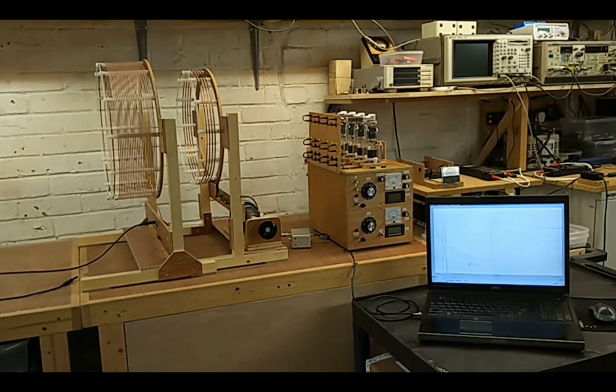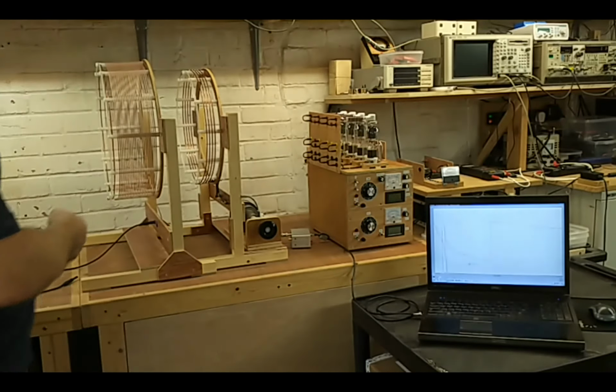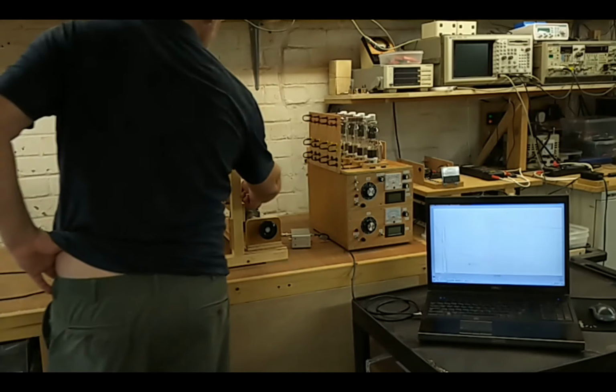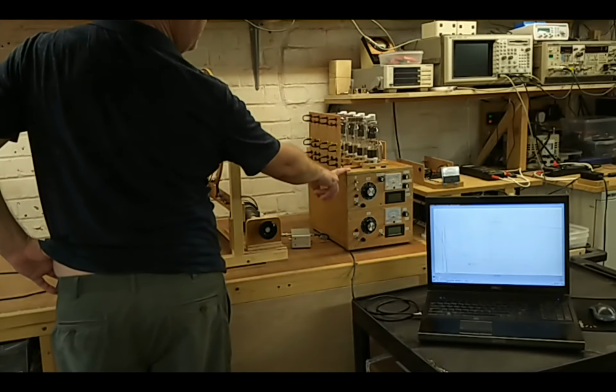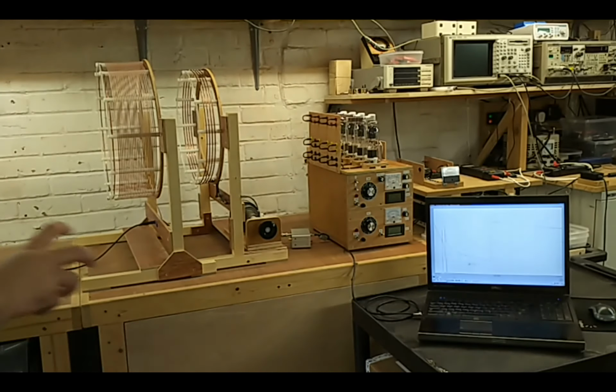at the impedance measurement. So this is all going to be about Z11, the small signal AC input impedance as seen at this point. So that's ultimately what the generator would see. If we had a generator attached, for example a vacuum tube generator like this, that is the impedance that the generator would see looking into the circuit.